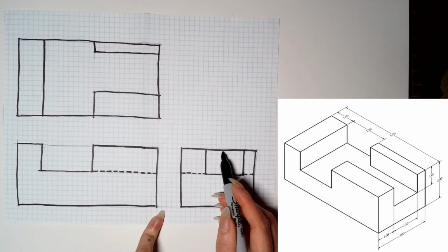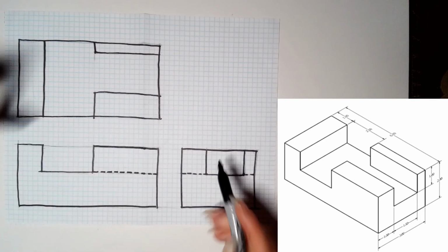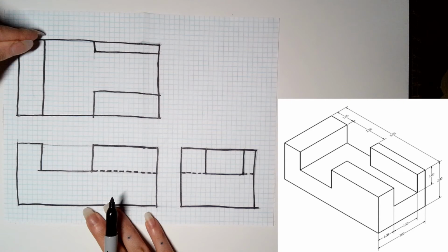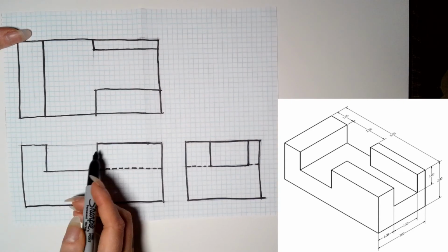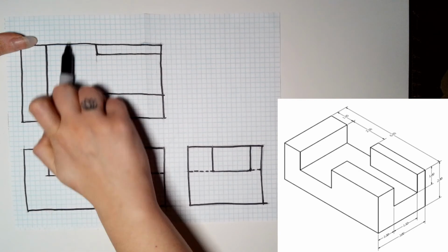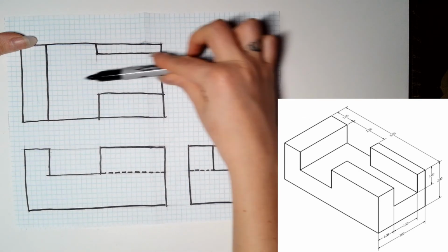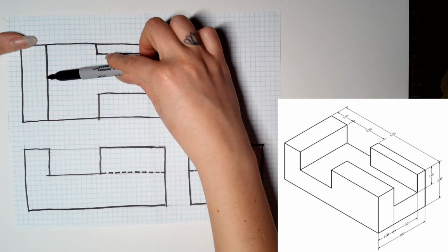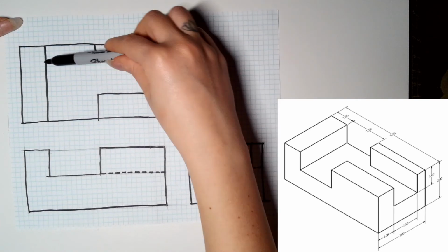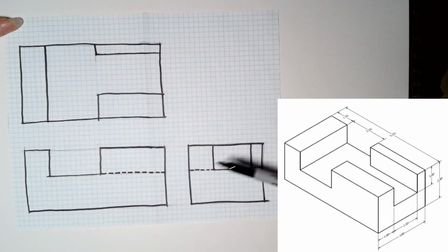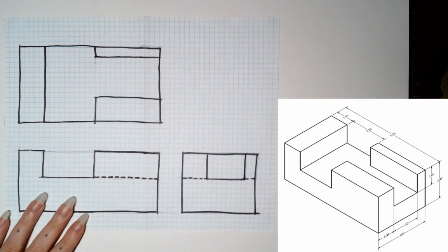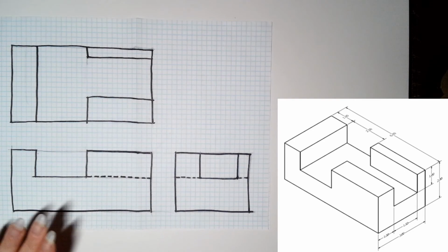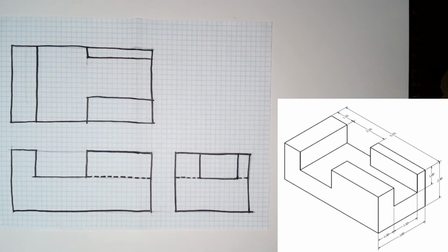This line here would still remain because this back face goes all the way through the object. The reason why there isn't a line up here on this one is because this slot goes all the way through. This one goes through and then hits right there. If this went all the way through on both ends, then that would be open on that side as well. And so that would be this object broken down as a 2D orthographic.